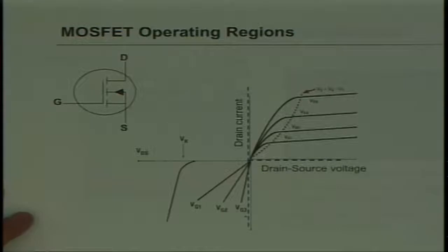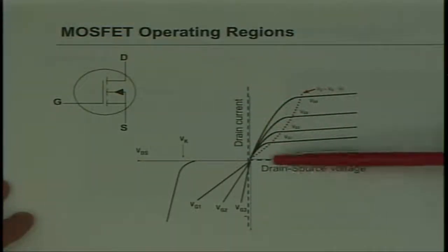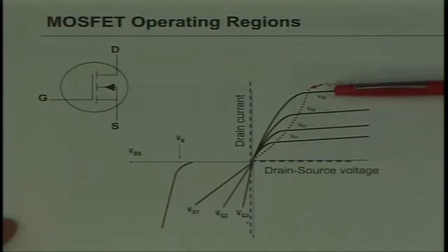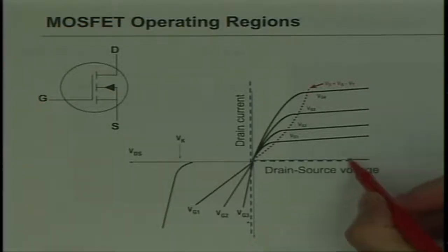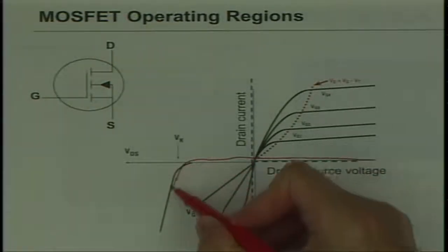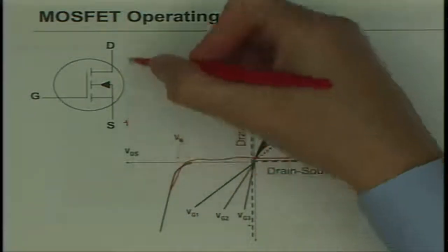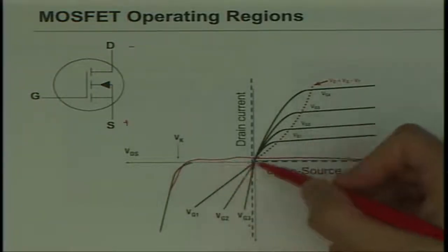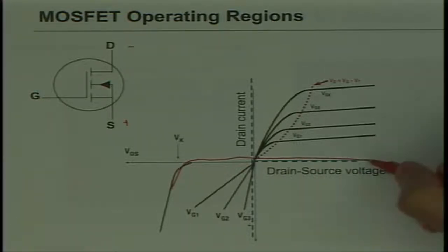So just a brief review, you've all seen the symbol for an N-channel MOSFET. This is their VI characteristic at various gate voltages. Normally, you're operating either here where it's off, and this is the body diode, so as the voltage becomes positive here and negative here, you reverse conduct with the body diode, and here's the knee voltage. And if it's off, you can go all the way up to its breakdown voltage way up here somewhere where it breaks down.